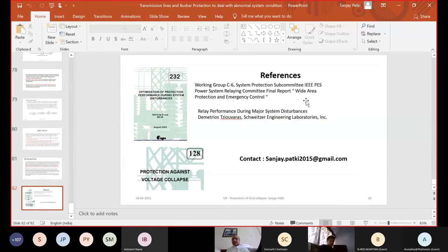No, it is not recommended, because Buchholz protection is not only for heavy faults where some other protection may also operate, but it also detects faults of incipient nature or even very minor core faults which slowly give rise to gases, and you can get a Buchholz alarm and trip. Historically, there are some cases where people did try overcurrent as a check to Buchholz, like a 2 out of 2 logic, which is what you are suggesting.